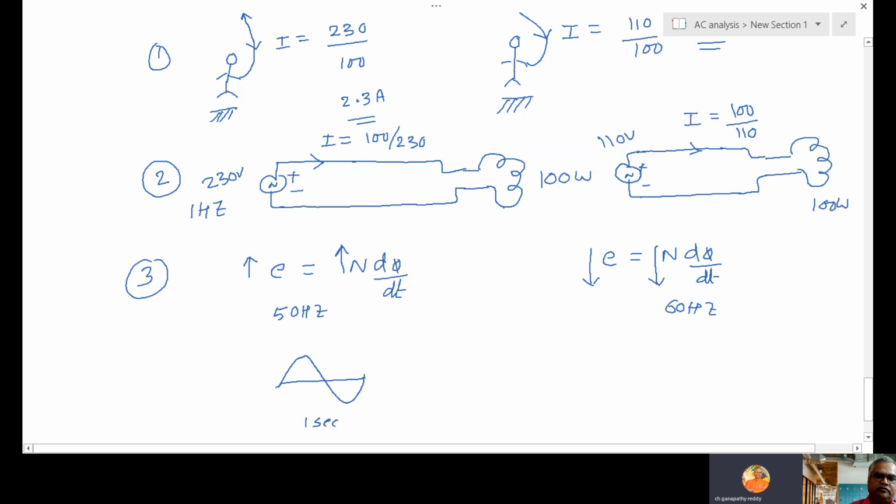So what is the bulb status at this time? Bulb is off. Here the bulb is fully on. Again fully off. Again completely on. Again off. This will come in the next cycle. So in one cycle, 2 times the bulb is fully on, 2 times fully off. So the bulb brightness is varying, and if you want to read under such a bulb, practically it is not possible. Now if you increase the frequency to 2 Hz, then 4 times the bulb is on, 4 times off.